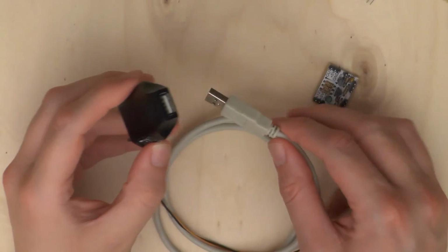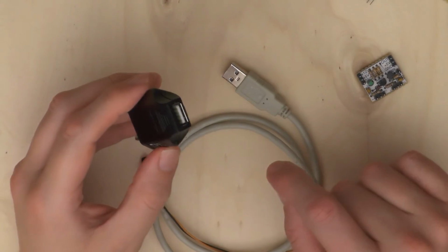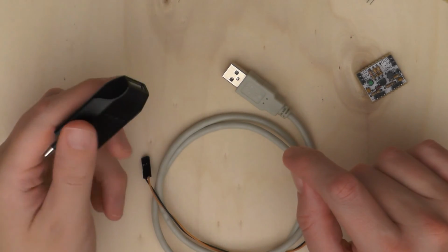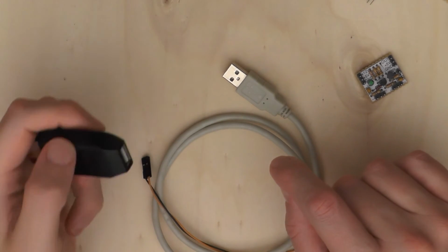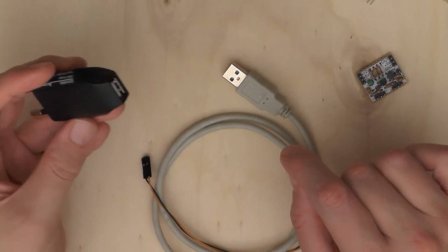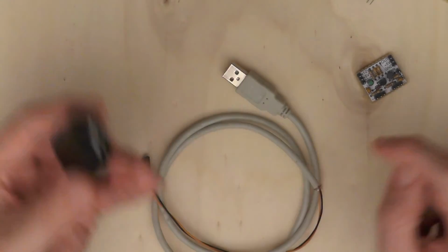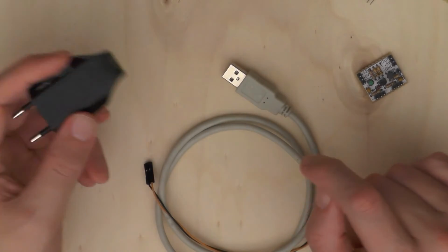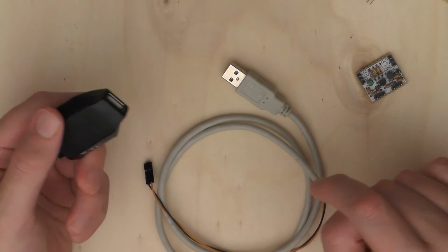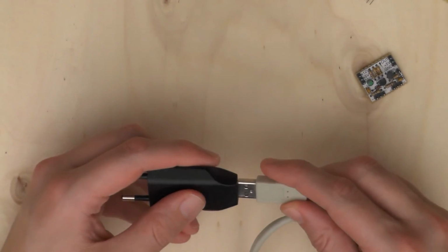Yeah, the reason why I didn't even bother to get myself a linear power supply, which I don't even have because I've never really needed one, was I wanted to make sure that this works if there's a switching power supply involved. So it doesn't make sense to test everything with a linear power supply and everything works fine, and then you hook it up to a noisier switching supply and things break again. So I'm using that.